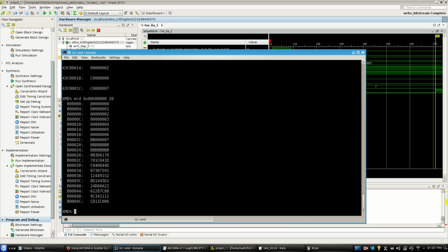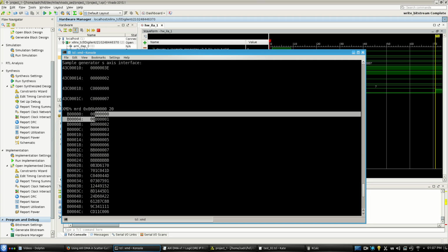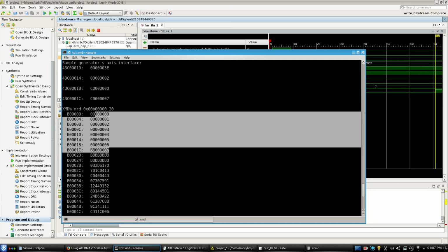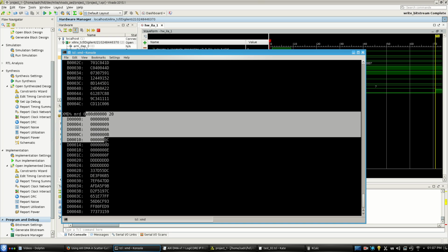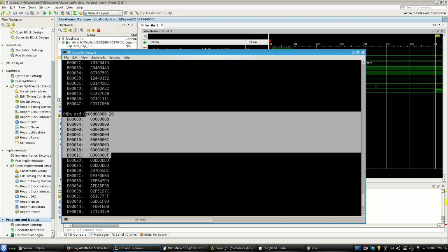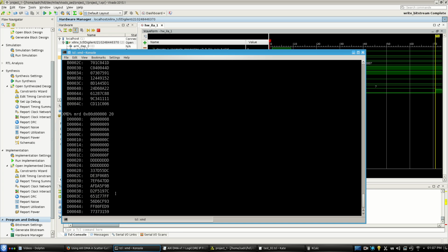I have, in fact, the first piece of S2MM data written here, and then the second piece of S2MM data, as per the descriptors that I have defined, and you can check for yourself later, is written here. I have instructed the DMA engine to write the first packet here, the first 31 bytes of data, and in the second descriptor I have instructed the DMA engine to write the second packet here. And as you see, for both of them 31 bytes of data is transferred.